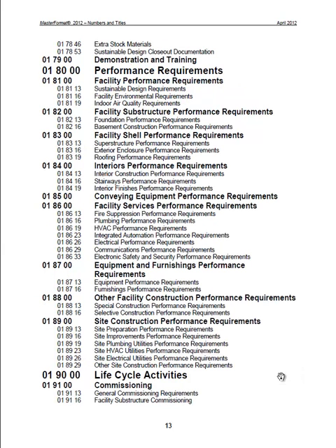Performance requirements, sometimes we do things like commissioning. This is where we hire an outside consultant to come in and test the air handling system and make sure that it's doing what it was designed to do, that the contractor hasn't made any shortcuts or wired a fan up backwards. And believe me, that happens more often than you think.